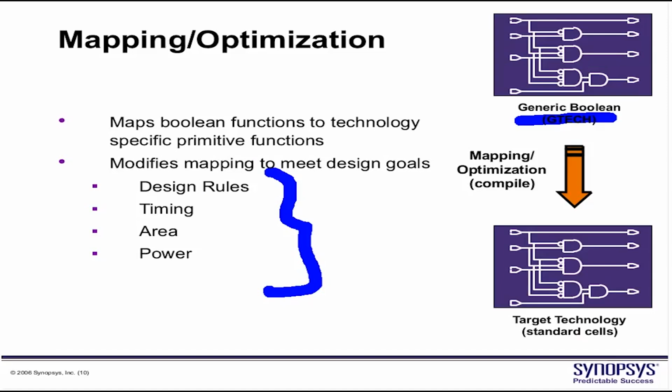So these 4 parameters are the key, and they are in fact in order of priority. So the design rules come first. We look into detail what design rules mean. Just a hint, it means that the gates, the logic circuit, the individual gates, let's say ANDs and ORs, NANDs and ORs, are not driving any load which is beyond their capability. This should be met first up.